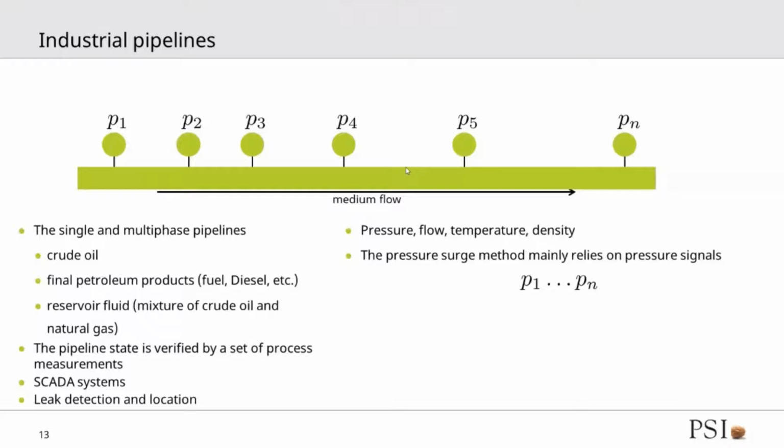And exactly in this particular moment, a mechanical wave is formed, the negative pressure wave, which travels in both directions, I mean, towards P4 and P5 with some speed, the pressure wave speed, which is actually quite similar to the sonic velocity, but not exactly the same, but this doesn't matter.